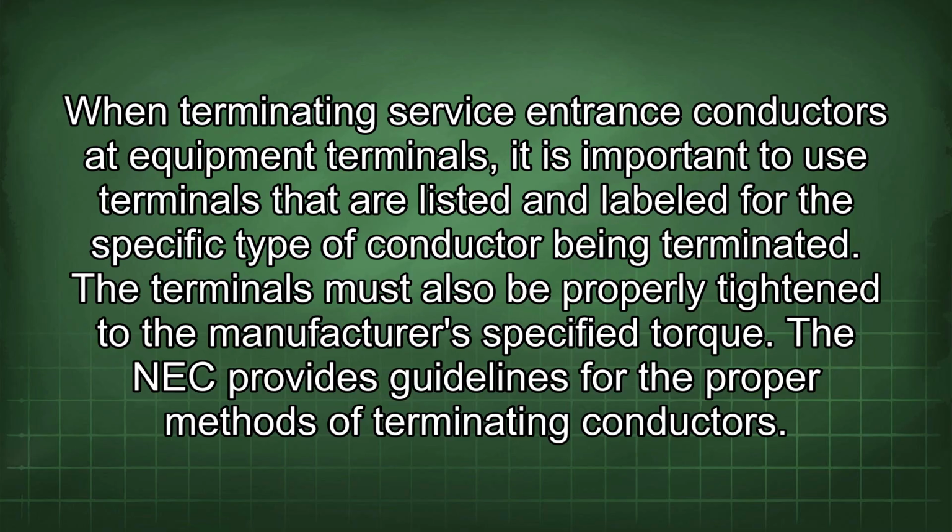When terminating service entrance conductors at equipment terminals, it is important to use terminals that are listed and labeled for the specific type of conductor being terminated. The terminals must also be properly tightened to the manufacturer's specified torque. The NEC provides guidelines for the proper methods of terminating conductors.